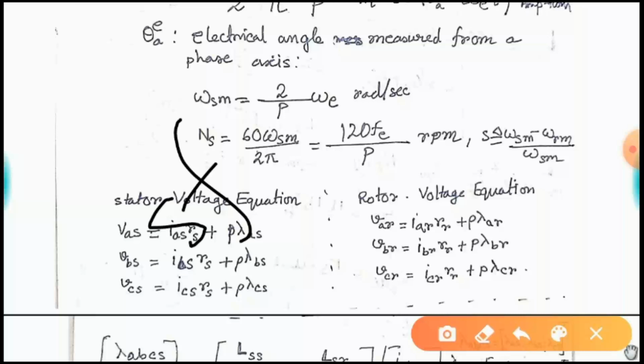The scheme is that you absorb power from the rotor circuit, which is the voltage sF, and by varying that rotor circuit voltage you can change the machine speed. I'm not going into detail on that. If time permits, I can share one video on that also, but it is not part of the present course.